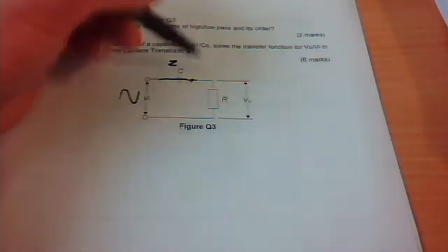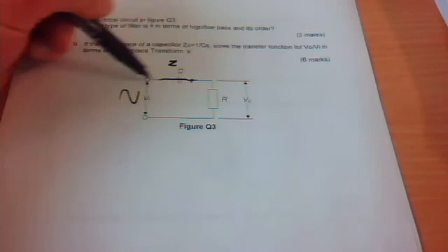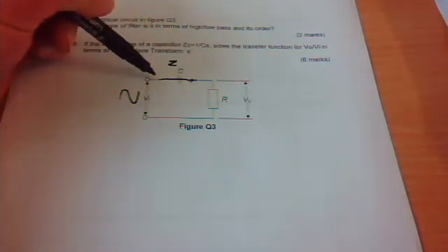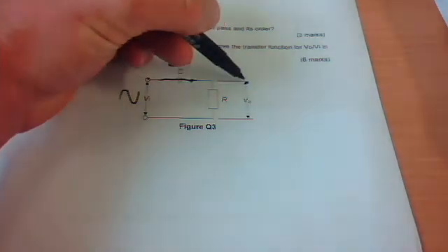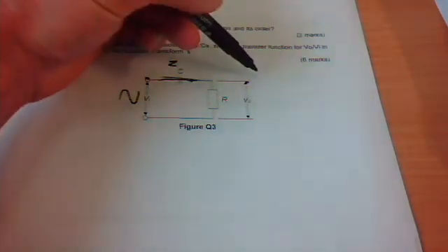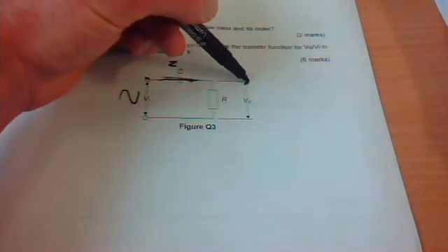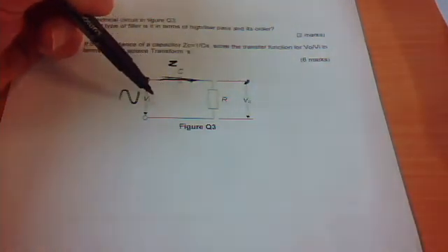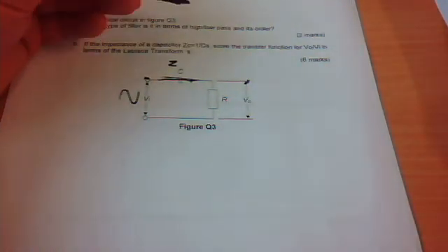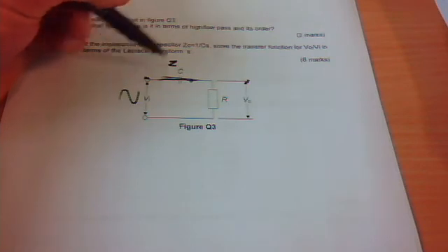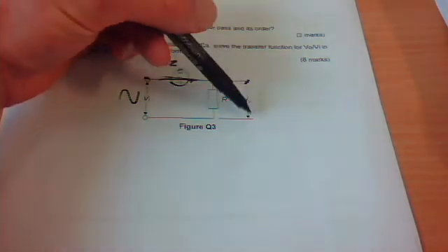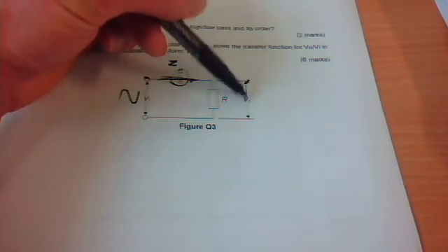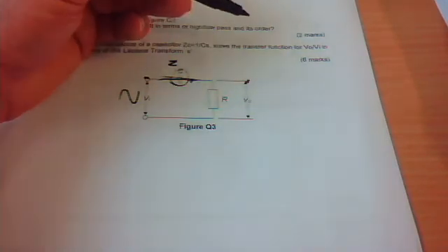Okay, so let's look at if we have a high frequency going through it. Then if that is a piece of wire, then V out is the same as V in. So you'll get a large voltage output, which would be the same as the input voltage. And if you've got a low frequency, then this becomes an open circuit. So basically you would get very little voltage output for a low frequency.